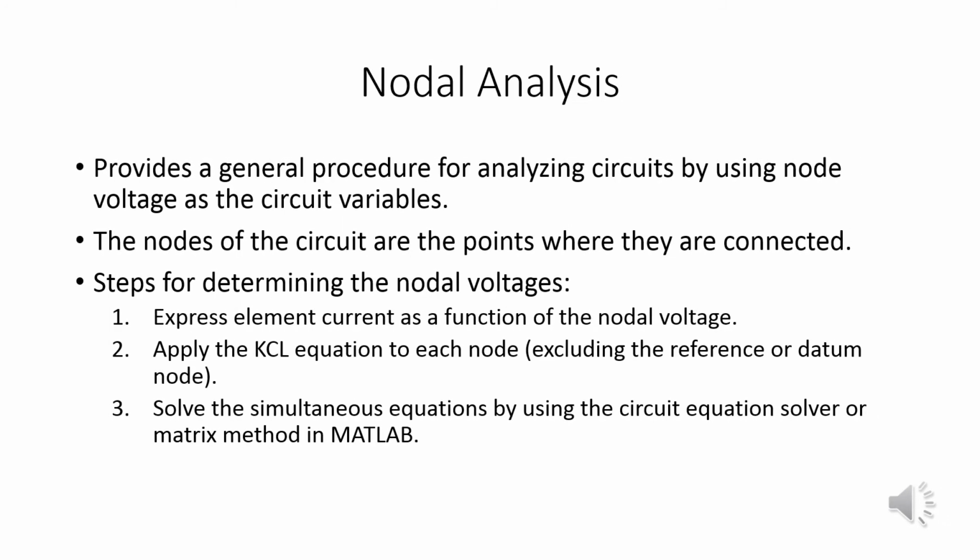For this next example, we're going to be using nodal analysis. Nodal analysis can be used to solve complex circuits by using the node voltage as the circuit variables. The nodes of the circuit are the places where they connect together. Analyzing the connected circuit containing nodes will require us to use the KCL equation. The KCL equation can be found from each node with the exception of any reference or datum nodes.